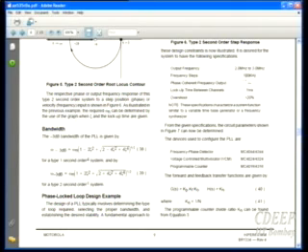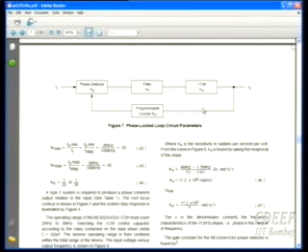So this is the frequency range, and then now this is overshoot. Overshoot means how much this control voltage of the VCO will have overshoot. Means what is the maximum frequency which is generated during the transient, because there is an oscillation in the frequency. So what is the maximum frequency? So you read this. It's similar, the same way that we have, like here we need to have a counter, and then what is the minimum value, maximum value, and then we will have an input frequency. So input frequency is constant, 100 kilohertz, therefore the steps of change of frequency are controlled by this counter.